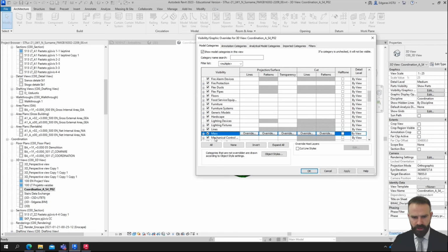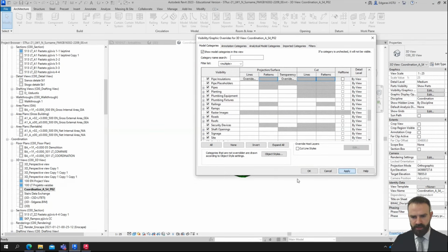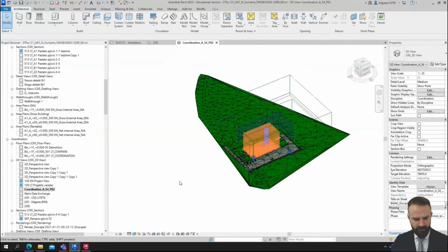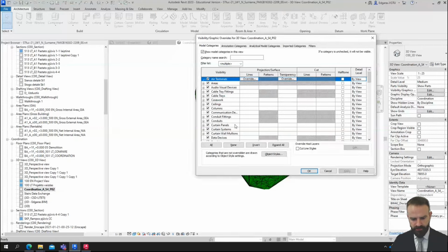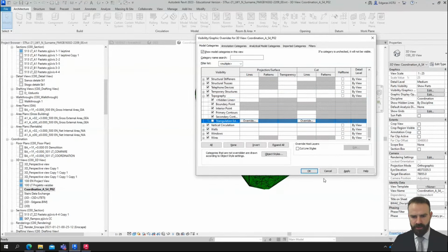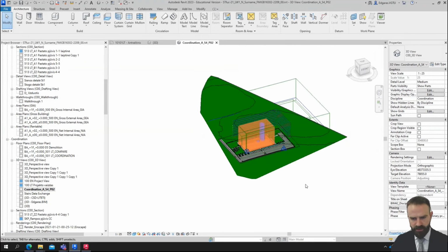And also I should activate mass objects so I can see the mass objects in my export file. So this is my file prepared for export, and also for topography, I can turn off triangulation so I can see only nice model like this one.